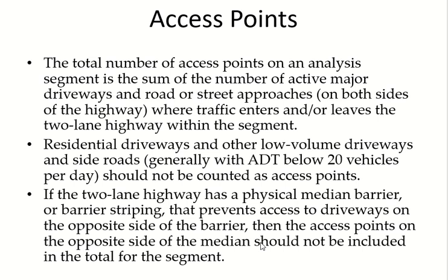These are called access points. So like we did for multi-lane highways, you count how many access points you have on your segment, divide by the length. Number of access points divided by the length. This is what you need in the analysis.